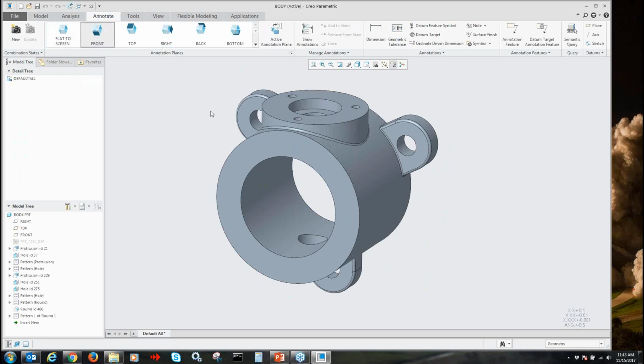And the process that I've gotten myself into over the past 2 years of discovering the MBD process, and how I can share this with some of my customers and our end customers, is to just have this visualization in the 3D model and have all of my data readily available. Just like we would in a detailed drawing, if you look across the bottom here, you see this default all tab that we currently have. We can build several tabs just like we would have on our detailed drawings in order to maintain and show what it is specifically that we're looking for and call out that information.